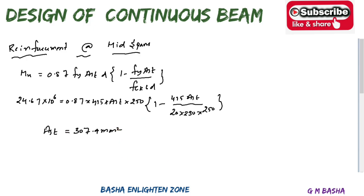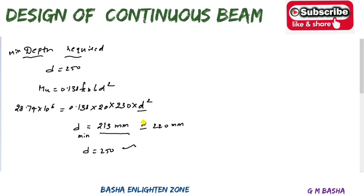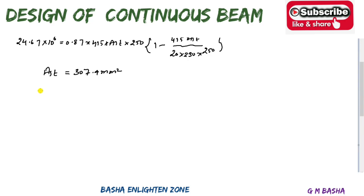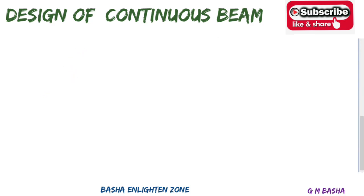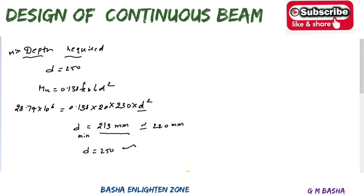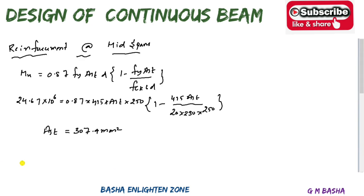I will tell you one more condition here. We already provided one area of the steel for this moment. This is around 4 bars of 12, which is 367 mm square. Here the moment will be 307. So the same area I will provide here. Here how many bars are we providing? Here we provided 4 bars of 12 dia. So area of the steel provided will be equal to 452.16 mm square. But here if you provide the same bars for this moment also, okay, no problem.